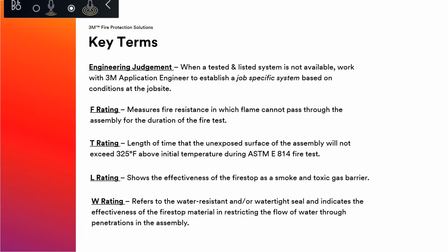So the system that you're referencing is going to identify that maximum hourly rating, that F rating. So if you have a situation on a job, maybe your walls are only 1 hour rated, but you're referencing a 4-hour system, just because the system says it's rated up to 4 hours doesn't necessarily mean that your 1 hour installation can still be achieved.